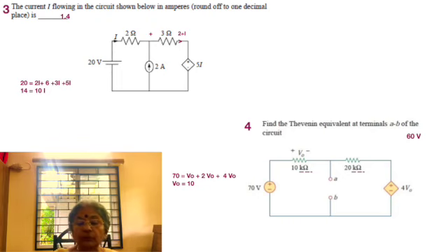You can go from the other side also, because 4V0 means 4 into 10, which is 40, and then you have to add 2V0 also, which is 20. So that's again 60. From either side you will get the total voltage, which is the Thevenin's equivalent voltage across AB, because AB is open circuit.